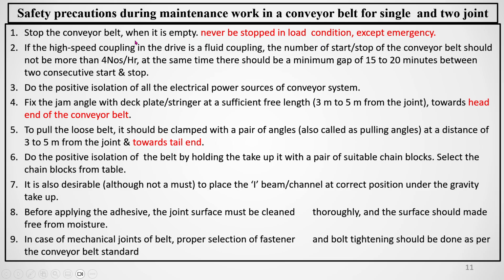So first of all, you have to remove all the material while it is in running condition, and then you stop the belt, except in an emergency, of course. If there is no emergency, then you remove all the material and then stop it for repairing.